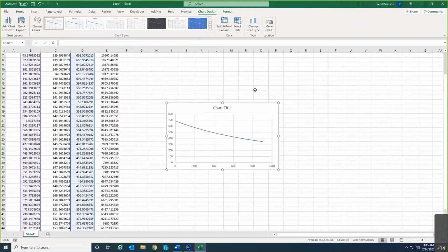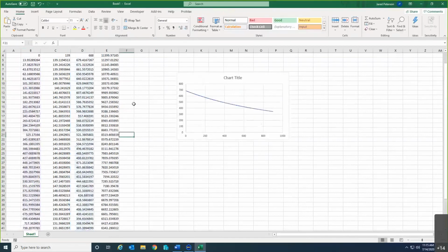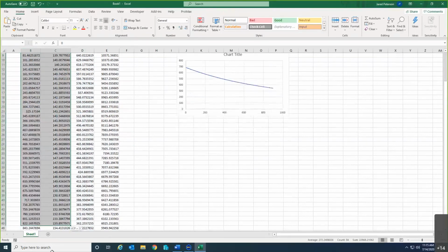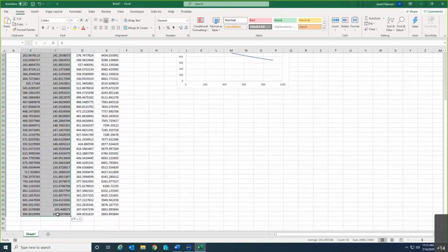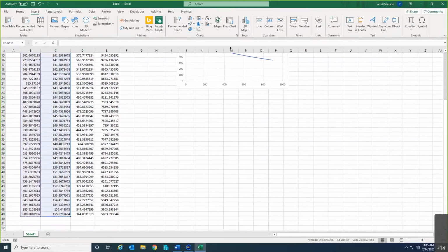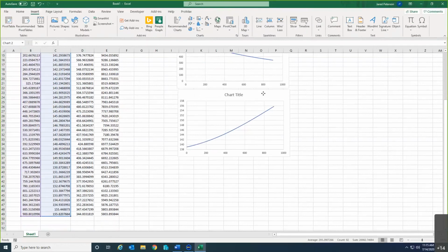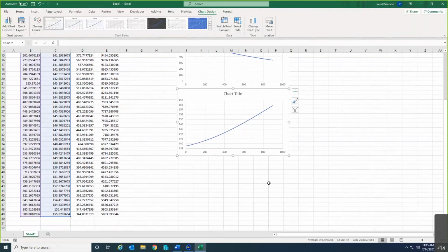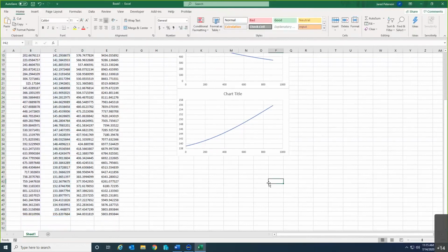We could look at, and this is going to be an interesting one, temperature as a function of time. You can see that it's actually increasing, even though I'm blowing down, even though I'm creating more vapor. That's because I'm adding energy to my system faster than it's losing enthalpy. The overall temperature of my system is getting hotter in this case.